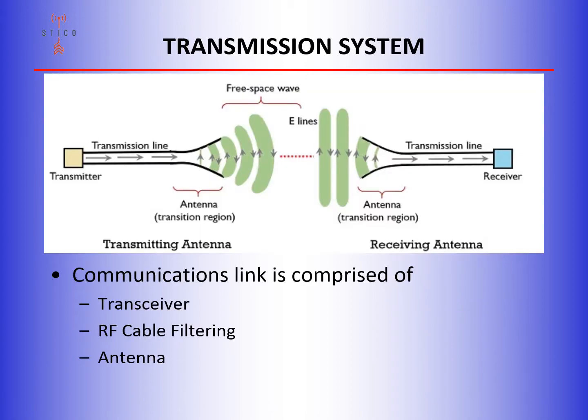A transmission system is comprised of three basic elements: the transmitter or receiver, the transmission line, and the antenna. To work correctly, these three items need to work together so that the maximum amount of energy possible is radiated in the proper direction. That is to say, each of these must match the other, otherwise we encounter losses in the system, and that energy that we want to use for increased range is wasted in the form of heat or radiated in a non-useful direction.